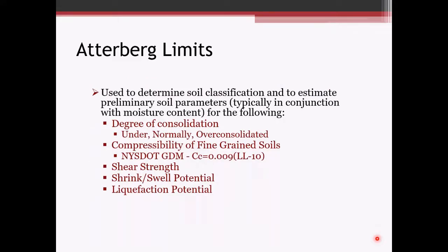And these are used to determine the soil classification and to estimate preliminary soil parameters, typically in conjunction with the moisture content for a degree of consolidation, to determine if the material is going to be under normally or over consolidated.